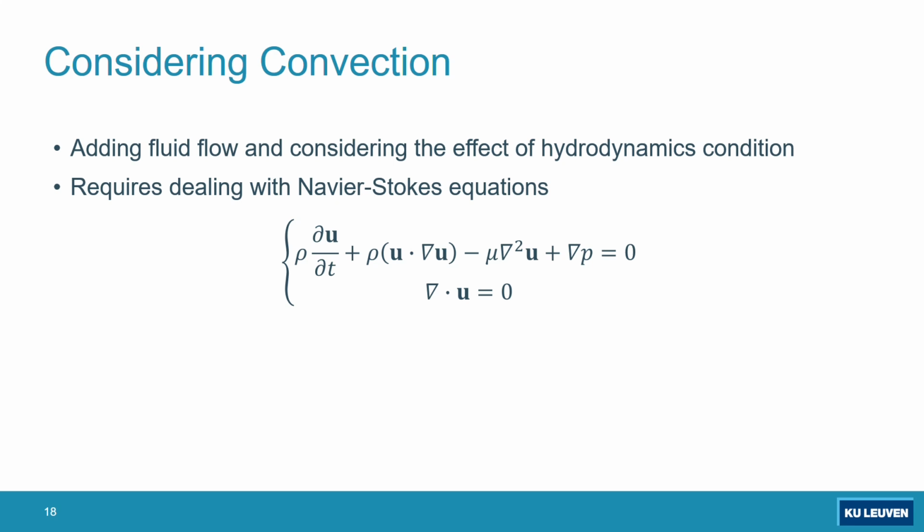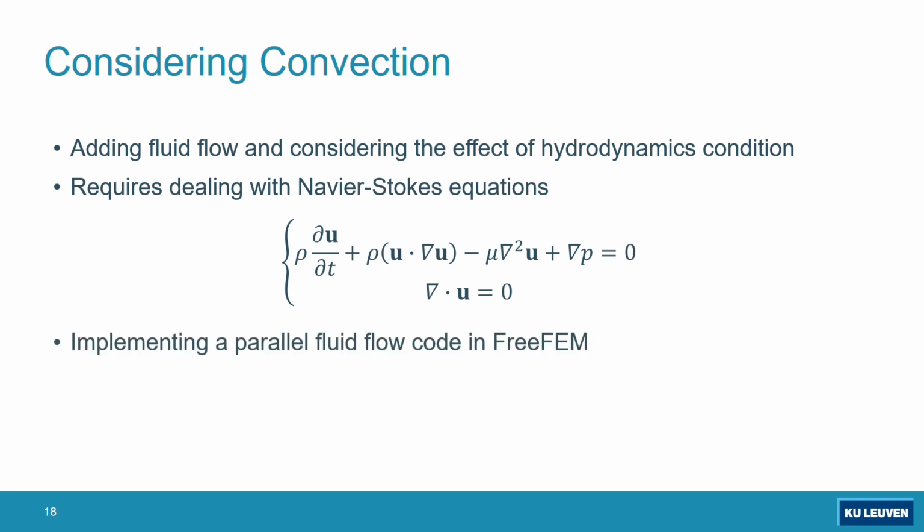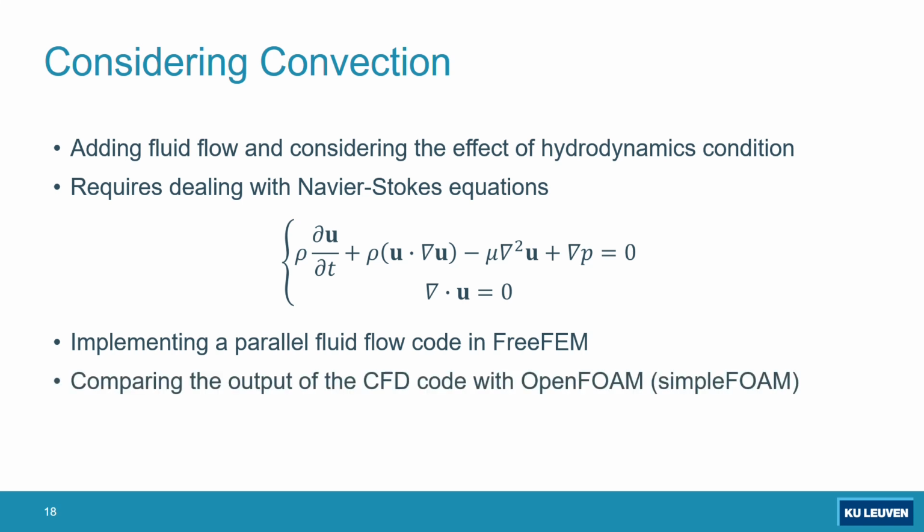That needs actually another kind of solver to couple with the basic model. This one is also implemented in freeform, so no coupling libraries are used. Everything is implemented in freeform in parallel, and then we also needed to compare results with another, let's say, less sophisticated CFD solver to be sure that the code that we have implemented works correctly.